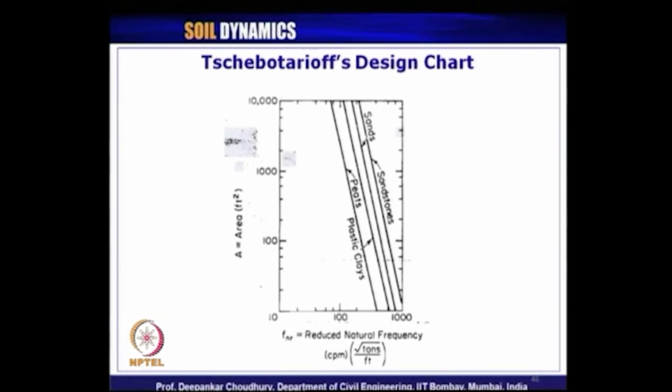And also, if you check carefully, if you try to derive the expression, you can also derive that these charts are not abruptly developed; these are based on G values of the soil. So, the slope of this line, the theta, you can calculate easily based on the G value of the soil.